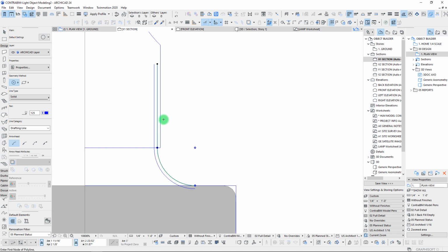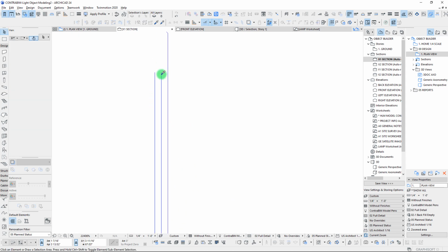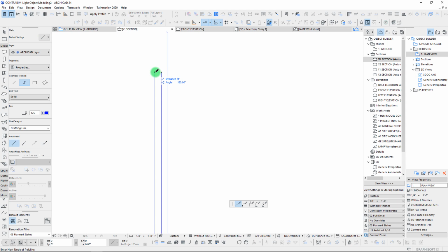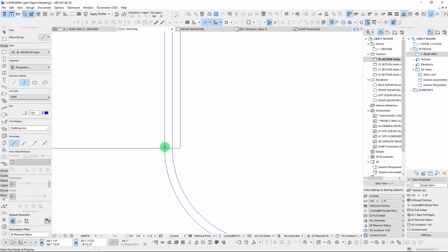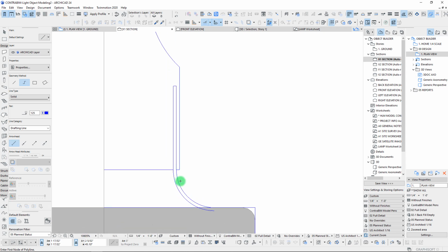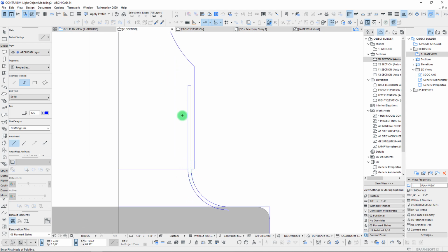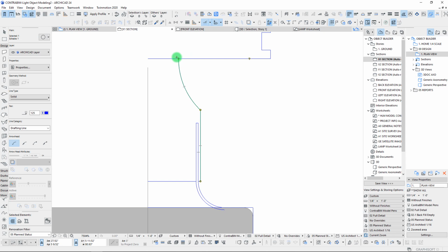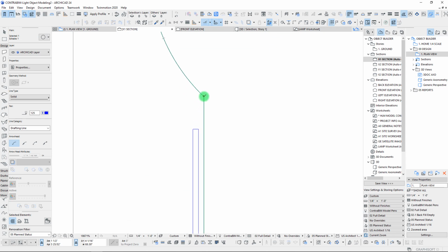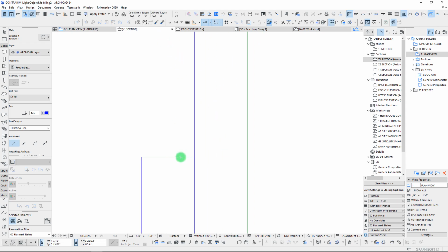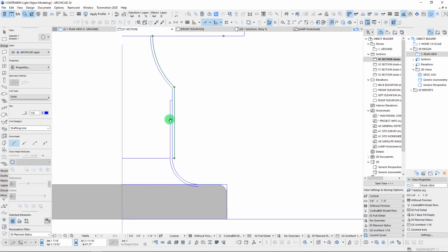So we have our copy there. And then I'm simply going to connect these at the top. And I'm going to hold down Control to just cut out that little segment right there. And so now we can actually take this whole thing, and let's do this for our next move as well up here. So we're going to take this, we're going to offset 1/16 of an inch. And I just want to see where it hits here. So it does hit exactly on.